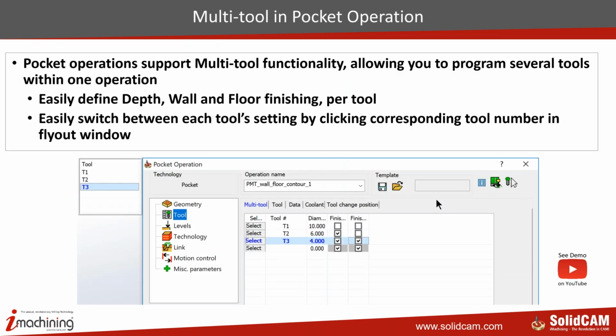We can also now use multi-tools inside pocket milling operations. When you're doing a pocket operation, it now supports the multi-tool function. As a programmer, you can use several tools inside one operation. You can define different tools: a different tool for roughing, a different tool for wall finish, a different tool for floor finish, and individually you can control the